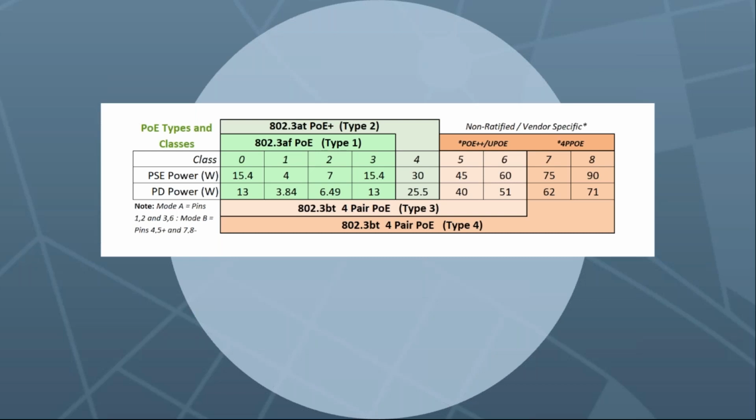In an effort to consolidate how much cable would be required, they designed an Ethernet cable that has 4 pairs or 8 wires. Each pair has a positive and negative, and you're able to run data and power through one cable. So that's eliminated the need for extra cable. What PoE does, initially it was 24 volt passive, and there wasn't really a standard.